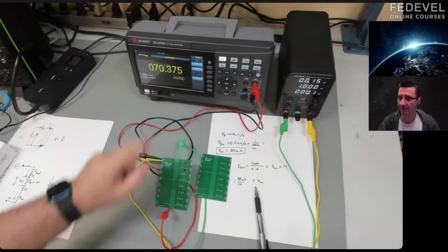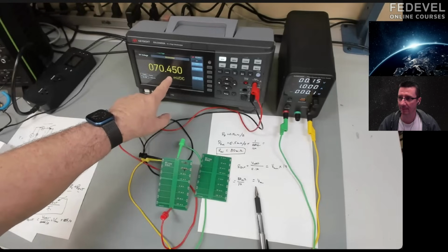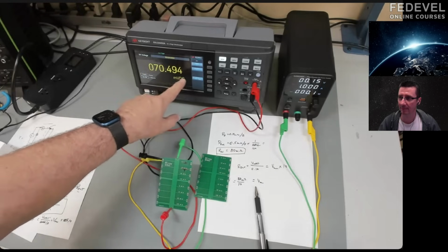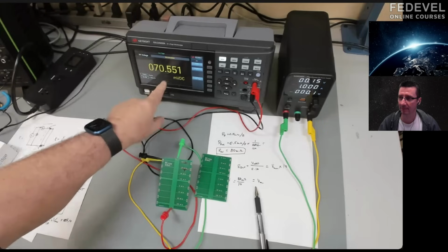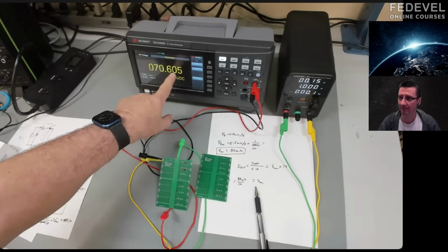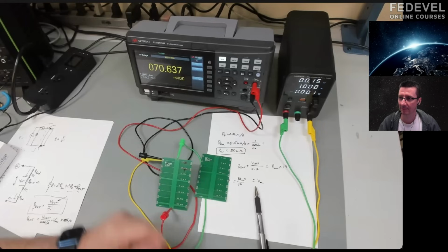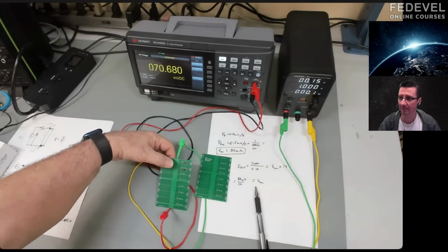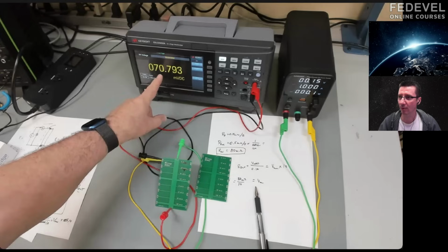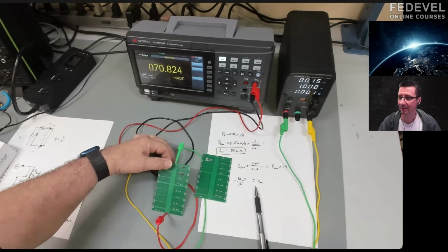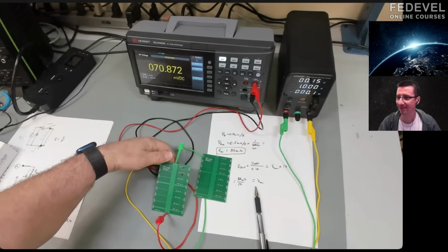And here it is. If you notice that voltage, it's going up a little bit, just a tiny bit, because we have such a great voltmeter here, and we can read so many digits. You can see it's going up a little bit. It's not constant. How come? If I touch the wire, what do you think is going to happen? Cool it down, very good. So the resistance is going to change. It's going to go down.